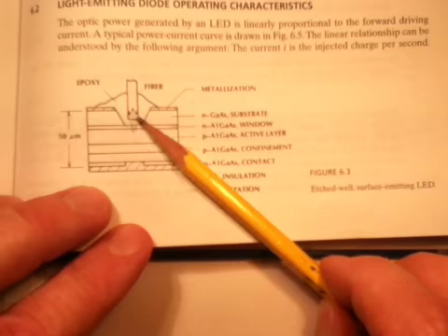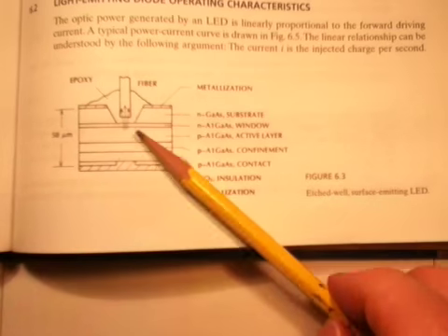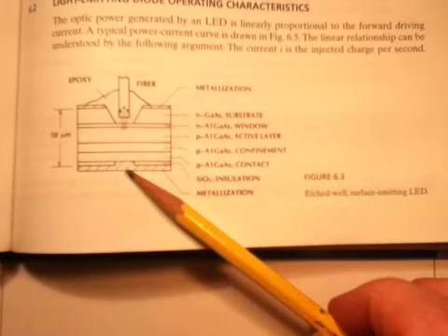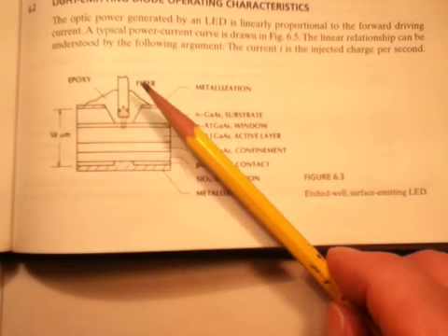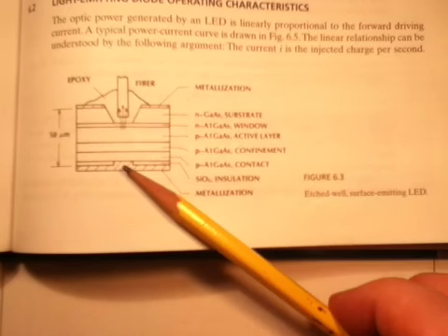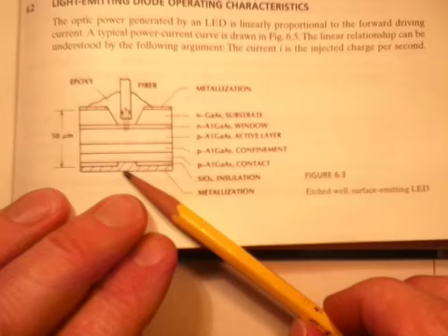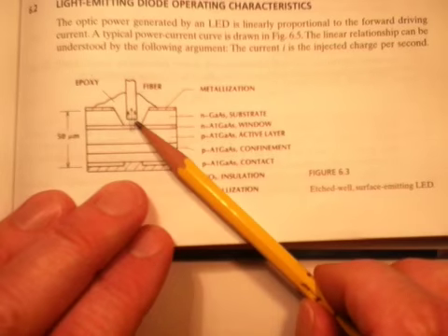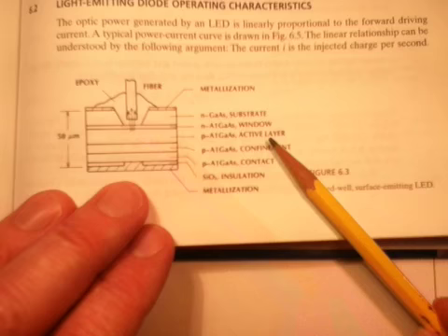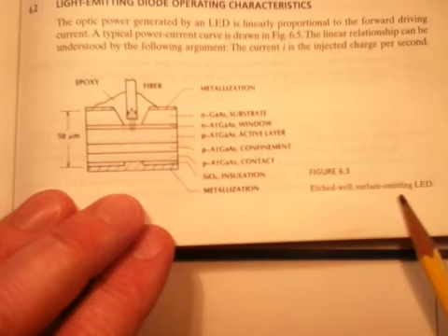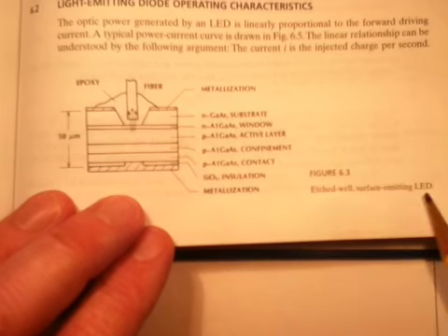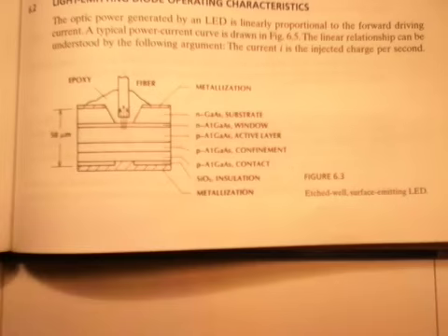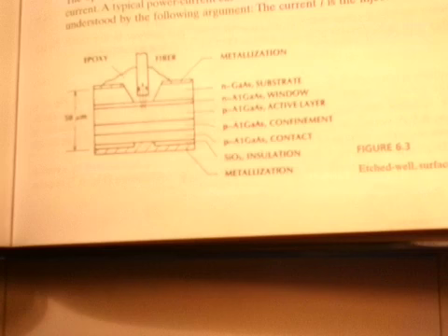And this can turn into a very high coupling efficiency and very low cost devices that are already fiber coupled and don't need to have anything fancy going on. No lenses are needed because we're butting the fiber directly up against this active layer almost. And so these are surface emitting LEDs, and they're a big thing in datacom applications.